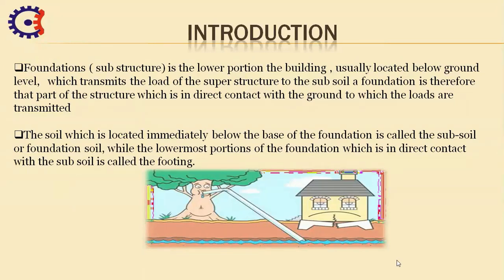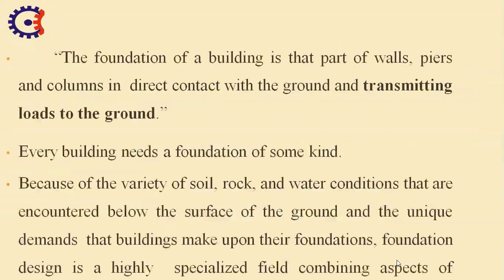Before constructing a foundation, footings are an important part of foundation construction. A footing is typically made of concrete with reinforcement that has been poured into an excavated trench. The purpose of a footing is to support the foundation and prevent settling. That's why we make footings.